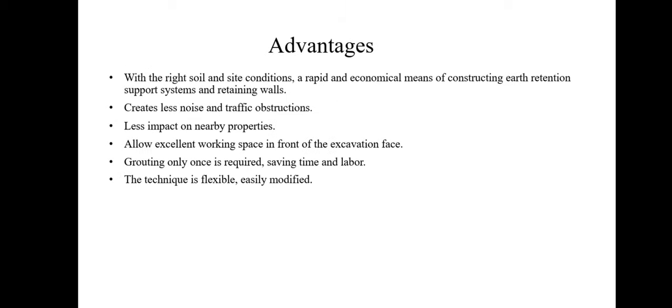So here are some advantages and disadvantages of soil nailing. Soil nailing creates less noise and traffic obstruction. And it has less impact on nearby properties such as buildings, factories, etc., because it creates less noise and does not require many big machines and other objects. This technique is also flexible, easily modified, and grouting is only required one time. It also saves time and labor.